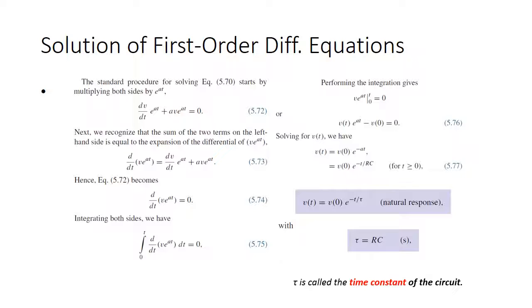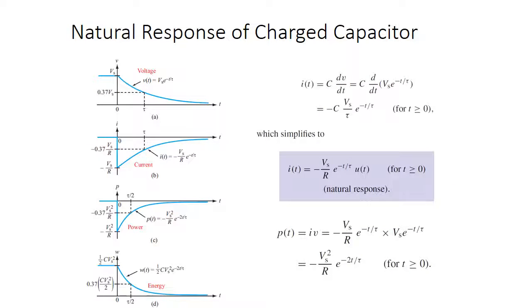If you just visually graph this, if you think of e^(-t/tau), and both of those R and C are defined, so it's a constant, it's minus t over a constant. That's going to look like an exponential decrease. So that's exactly what you would expect from a circuit where the current is being provided by your capacitor. So here we're going to look at exactly what I was saying from a visualization standpoint.